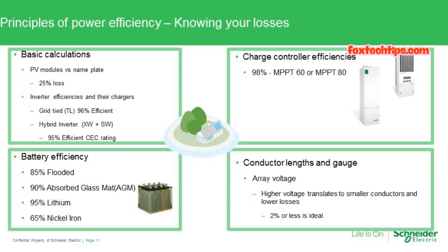It can surprise you when you start making a bunch of bends and going around corners and things like that. That distance can become quite a bit further than maybe just at first glance a less experienced person could expect. So upsizing and going with larger gauge wires to reduce that loss through conductor lengths is important.